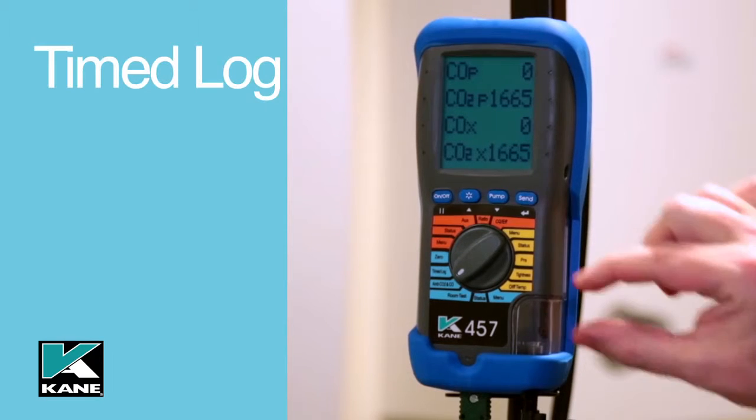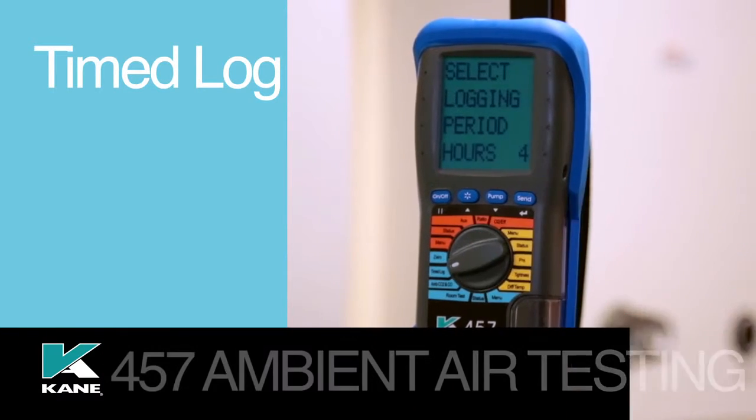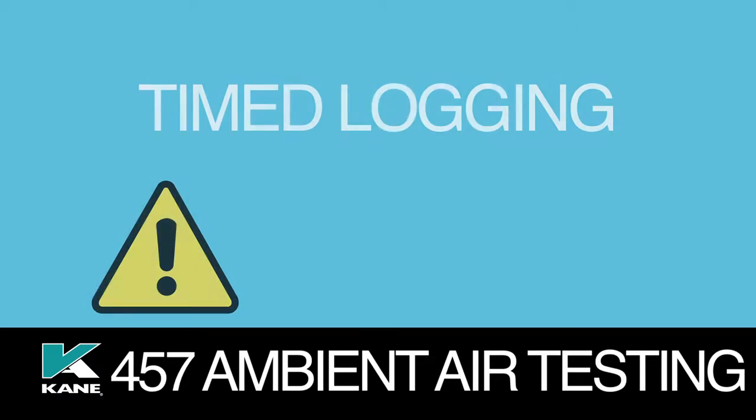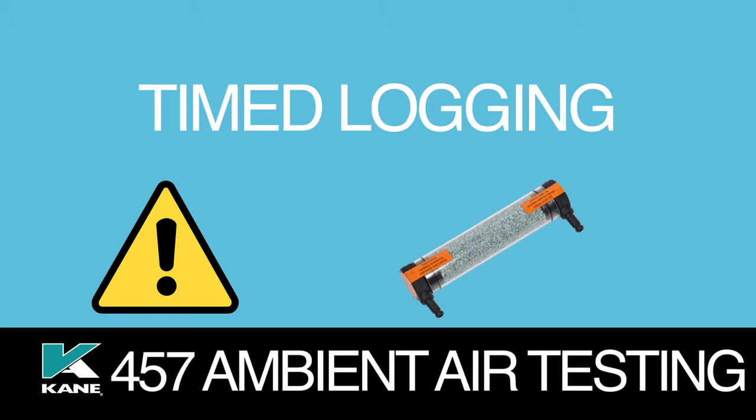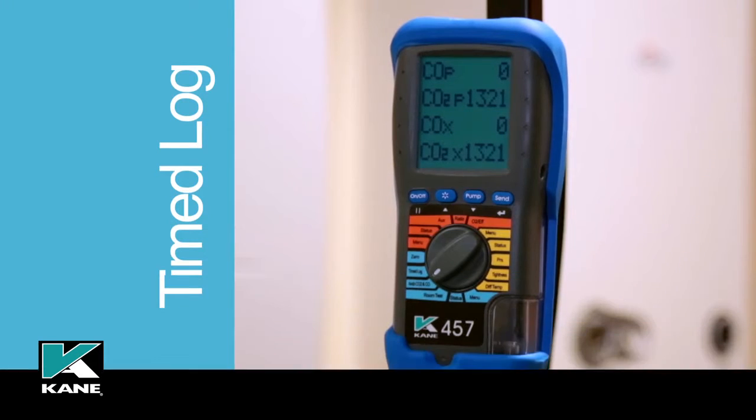The next position is timed logging. Note, before carrying out this test and to ensure accurate ambient measurements of CO2, the KANE457 should always be zeroed using a zero cal capsule. We will demonstrate how to do this in a few minutes.